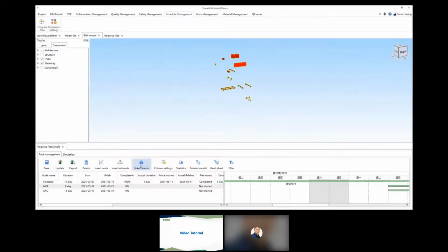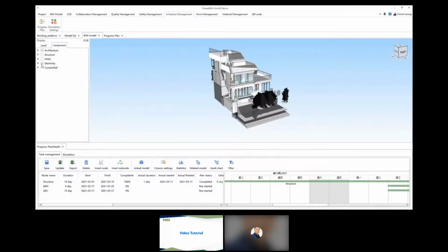Select All. Click Link Model. Then right click on the highlighted parts. Yes to associate. Repeat for architecture. Again, save often. We can also include or exclude families to the node. In this example, we will include all.